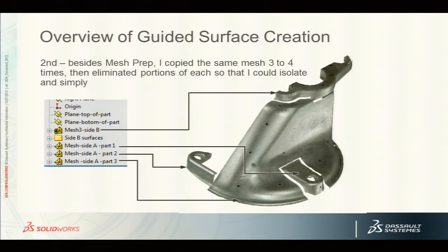So what I do is go into my surface mesh wizard and I cut it in half. I remove half that mesh, but before I do that, I copy 2 more instances of that mesh. The reason I do that is then I have meshes that identify different areas that I want to work on, but also those non-symmetrical areas. So you can see that that mounting tab on the left side is the only non-symmetrical part of this part.